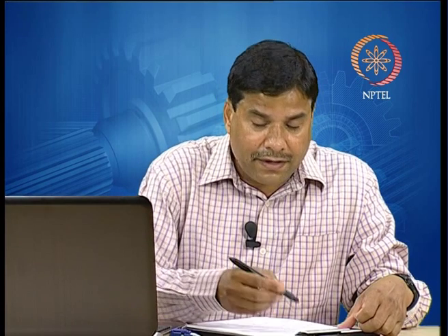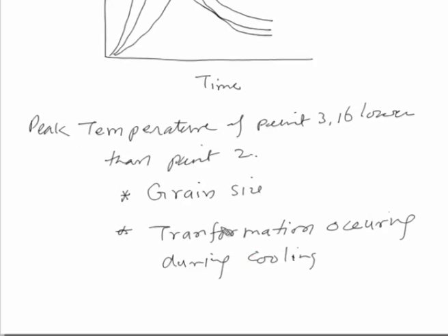In general, the higher the temperature of the metal, the greater will be the coarsening of the grains in the heat affected zone, and this in the case of steel will facilitate the transformation of austenite into martensite. So, those regions which are subjected to the higher peak temperature result in a coarser grain structure, and coarse grain structure generally leads to the development of martensitic transformation in the case of hardenable steels.